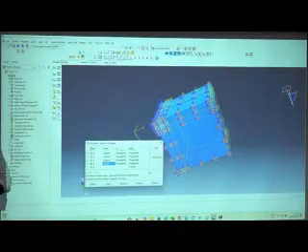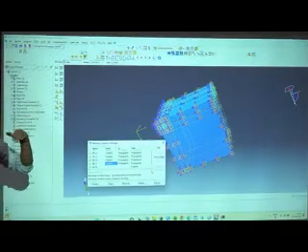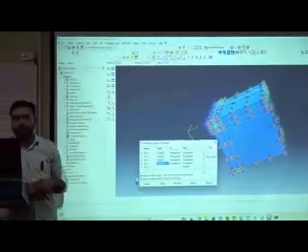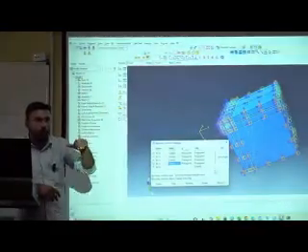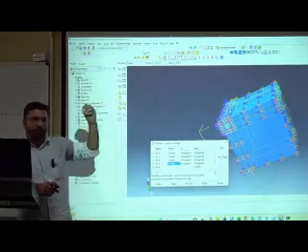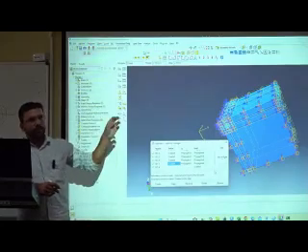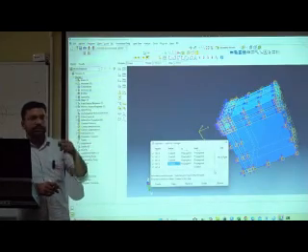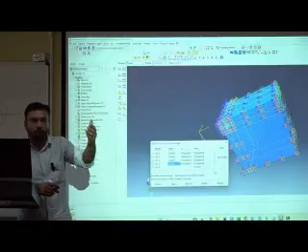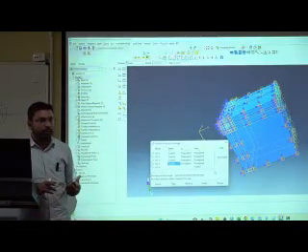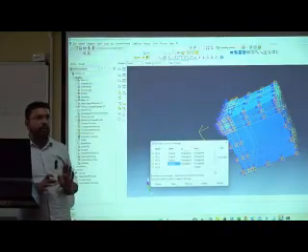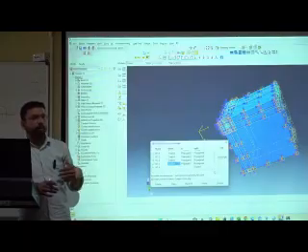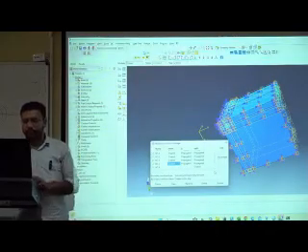Then Plaxis gives two options. One is prescribed displacement. You apply a displacement like 100 mm; your pile raft foundation or your pile will go up to 100 mm displacement, and whatever load is there, it will be noted automatically. The second is the load. You apply a load like 100 kilonewton per square meter. According to that load, the displacement will come and it will be noted automatically, and you can draw the load settlement curves from there.